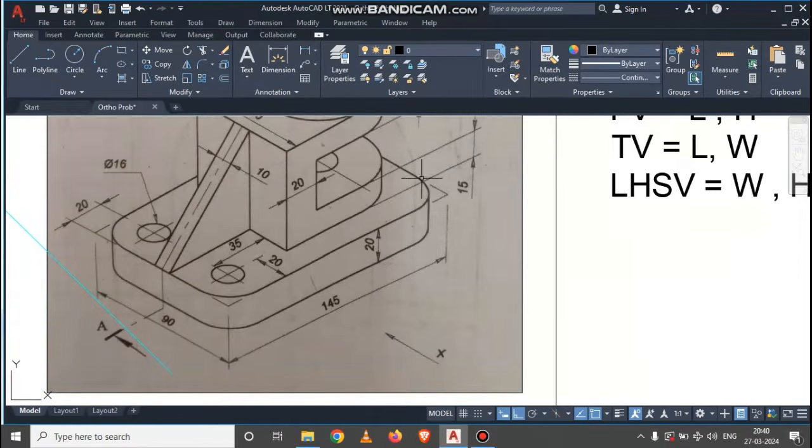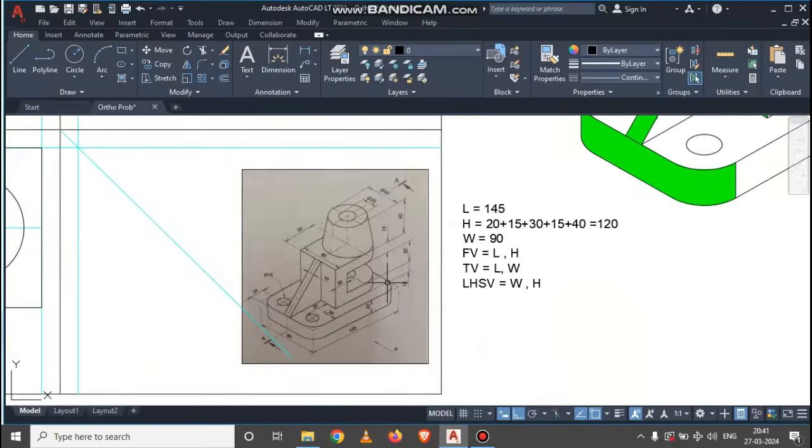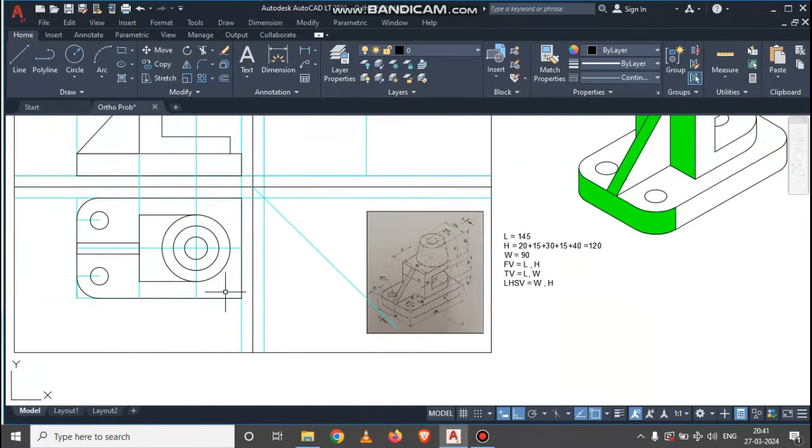So to get the remaining fillet curves on the other end, we need to find the midpoint of this total rectangle, and over there we are going to draw one vertical line so that we can have the mirror image of these two fillet curves. Go with the projection layer, go with the line command. Somewhat over here we are getting the midpoint, so this will be the starting point, and this is nothing but the midpoint of that total rectangle. You can imagine the vertical line over there. Select the mirror command, select these two fillet curves, press enter and use this vertical line as an axis for the mirror, and press enter.